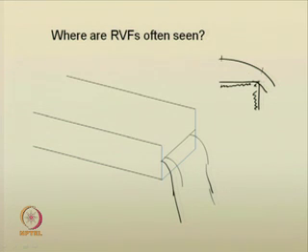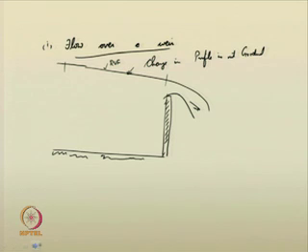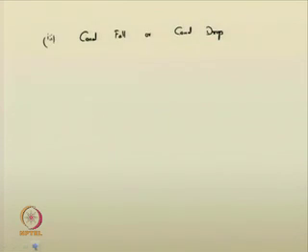In this entire stretch it is having rapidly varied flow. This is also a rapidly varied flow profile along the drop. So, you can see such phenomena in rapidly varied flow. The most important of the rapidly varied flow profiles is the hydraulic jump.